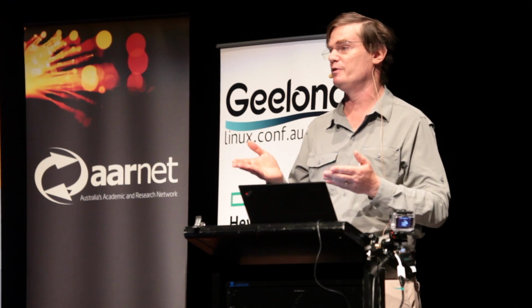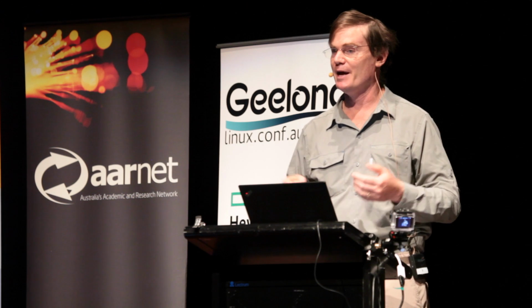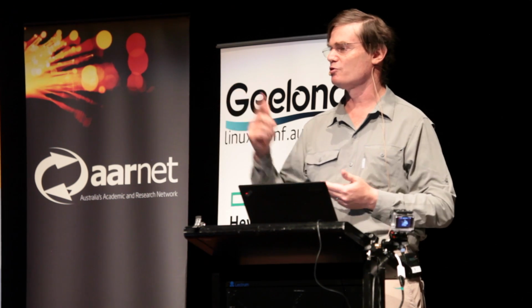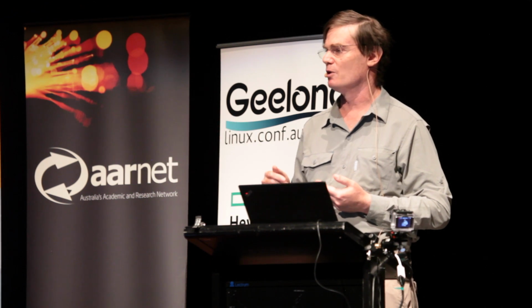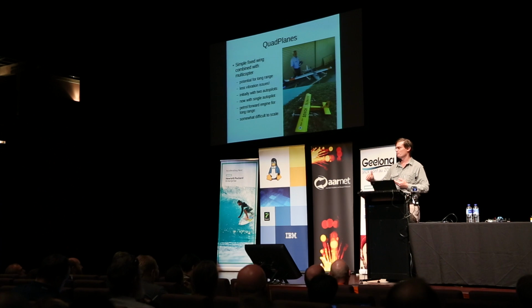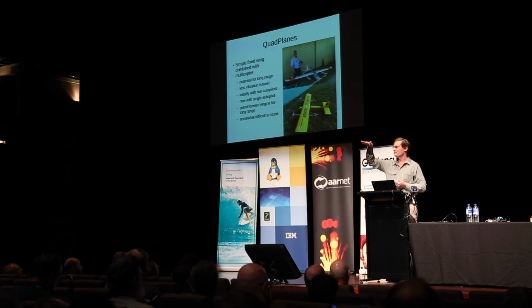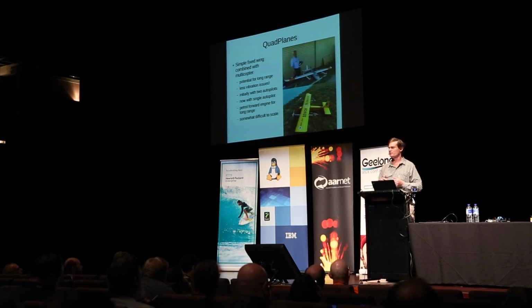And so the very first time we tried it, we actually just fitted 2 flight controllers. So we had 2 autopilots in that yellow plane, and we had 2 pilots on the ground with 2 RC controls, one of them controlling the fixed wing and the other one controlling the quadcopter autopilot. And what happened was the quadcopter person just said, take off, and then just puts it into hover, right? And then tells the guy on the controls for the fixed wing to say, okay, start advancing the throttle and flying. And he started advancing the throttle and it flew forward and went off beautifully.